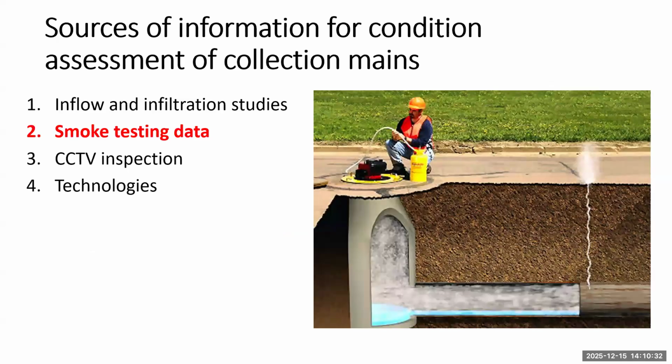We're going to go on to a different way of inspecting, which is smoke testing. The inflow and infiltration studies require some equipment and some time. Smoke testing uses relatively simple equipment, and it gives you immediate data. It's usually something that operators can do when they have a day that they can spend on doing this. You don't necessarily have to have a specialist come in like you might have to do with inflow and infiltration studies. And you could see an operator in this image on the slide.